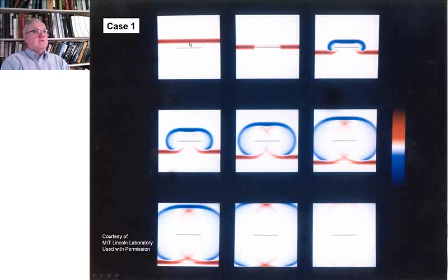You see first that the field comes in. Here it's right at the plane wave. What you've really got is the current canceling out the plane wave. And here we have the induced current in the metallic surface has given rise to an electric field with negative sign, as you get when you bounce that polarization off of a metallic conductor. We saw that in propagation when multipath would bounce off the ground. It'd flip the phase to -1. That's that -1 we're seeing.